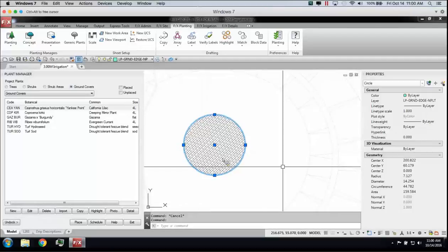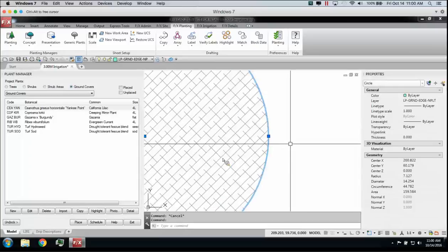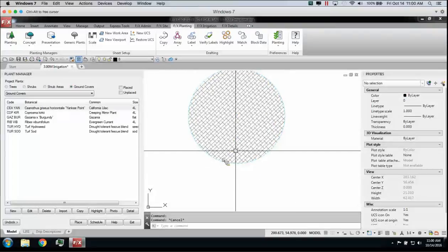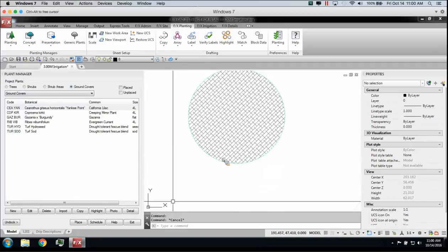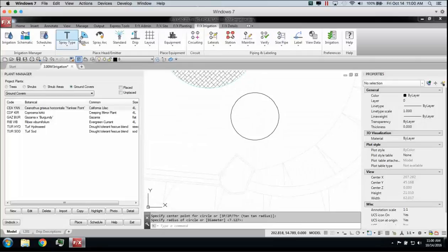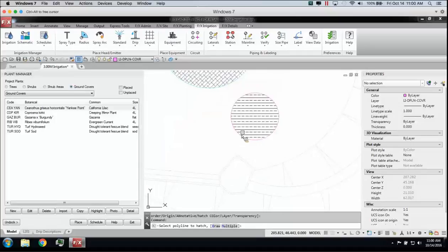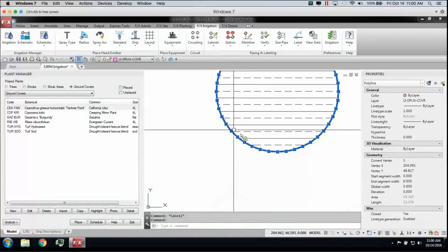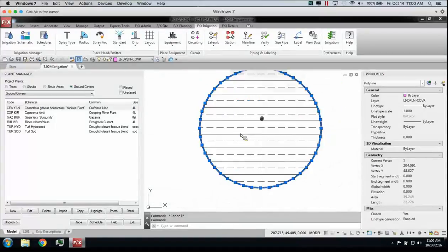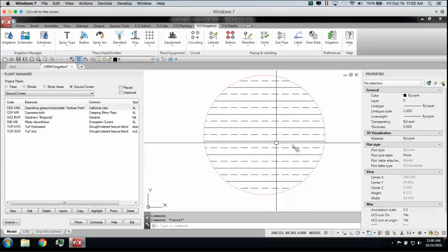All right, now I might have to check. That is integrated in there, the ability to do the circle to poly. And I wonder if maybe it's just the drip area. I'm going to try one last try here before I make a total fool of myself. Was it for the drip areas? There we go. That's what it was. I'm so sorry. So for the drip areas, it needs that outside area to be a polyline. And so I just integrated that into the placing hatch.